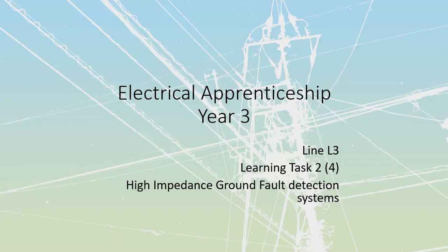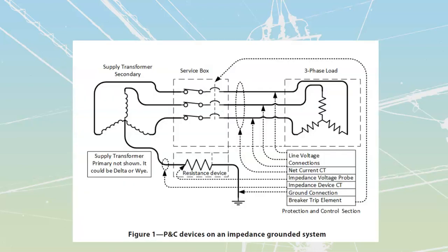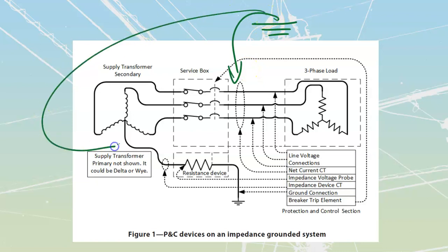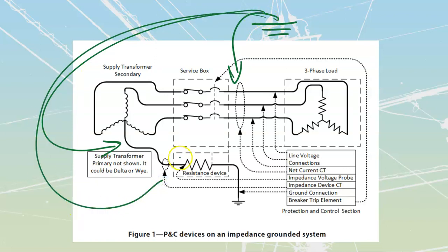You have to know if you have a ground fault on any one of your lines. So if any of these lines goes out to a ground, we need to know about that. We need to know if we have a ground fault on the neutral that we have over here. We also need to know if we have a ground fault on our impedance, our line that goes between the impedance device and the neutral, or if we lose continuity across here, if this thing actually opens up.